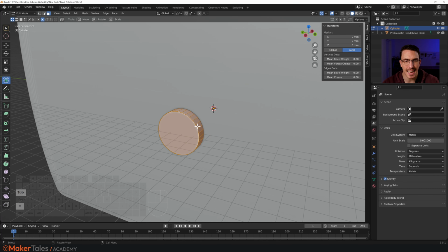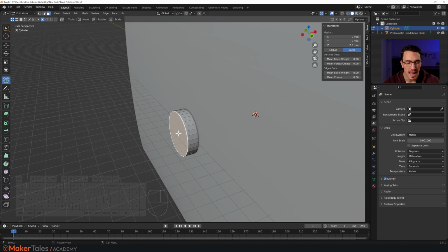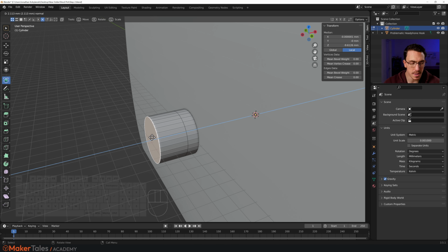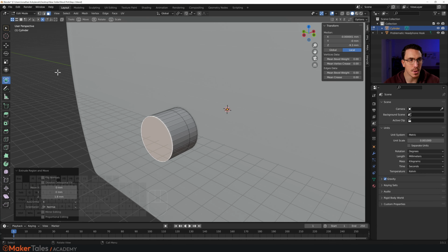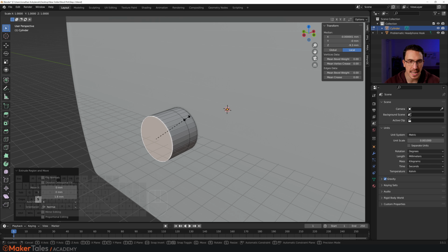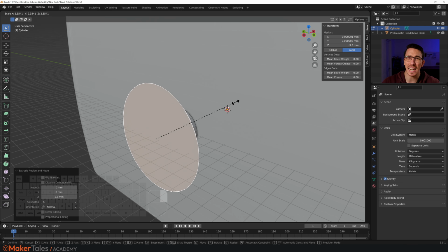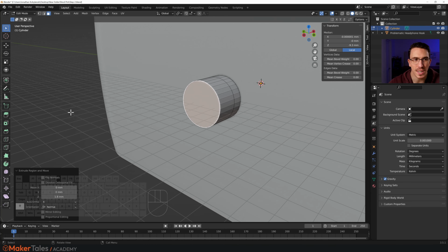I'm going to take this into edit mode. I'll select this face here, and let's create that screw part that opens up. So extrude this out. Let's go by 1.8 once again. I could now press W for my normal selection and press S to just scale that, but that's not exactly precise. Let's bring some precision into this now.